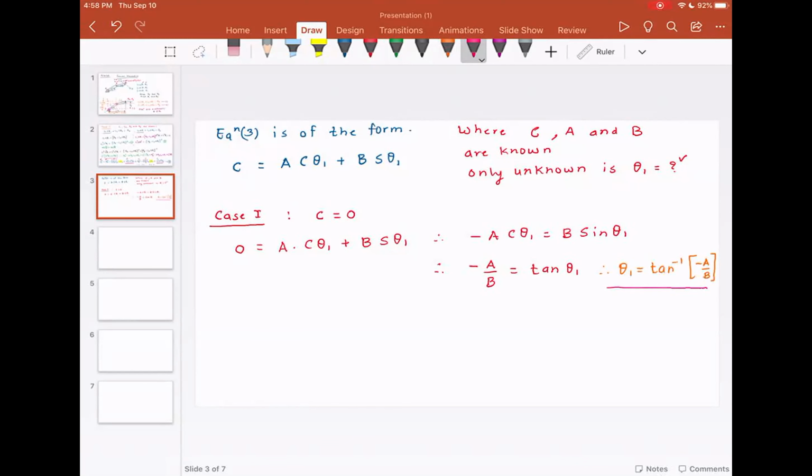So now you have a tan inverse, but the tan function does not work in all 4 quadrants. And please understand that the robot could have more than one solution, or solutions that are in two different quadrants.